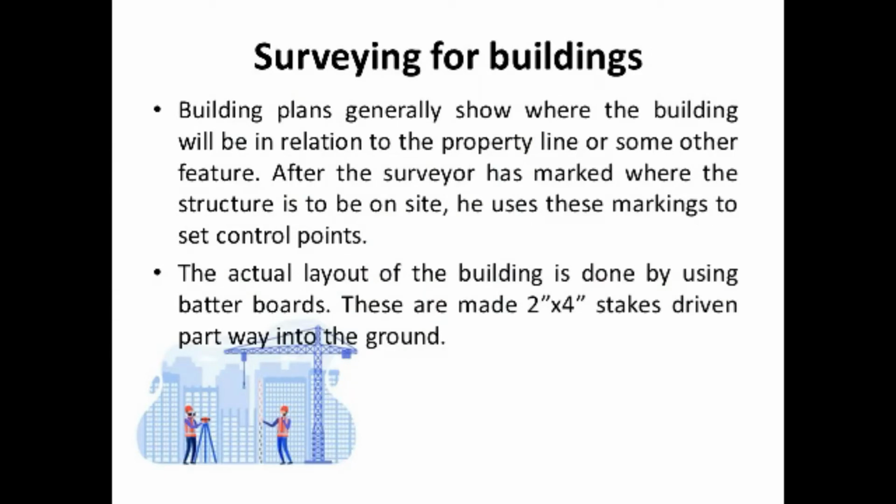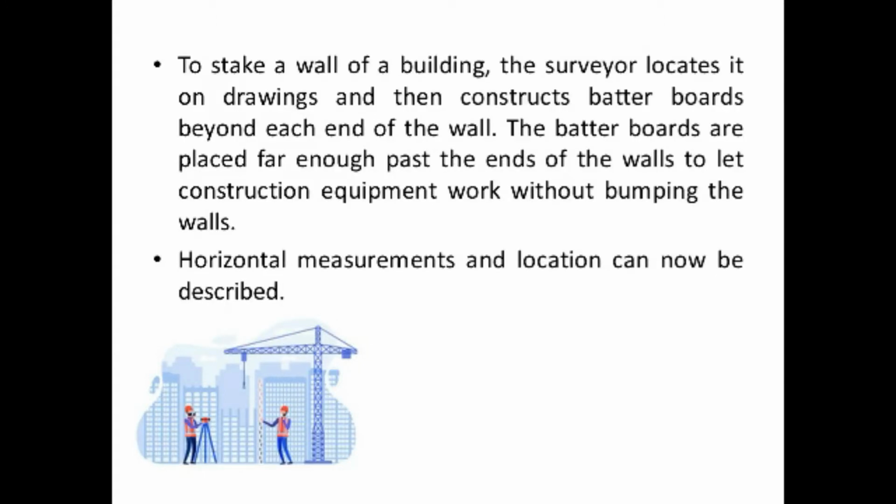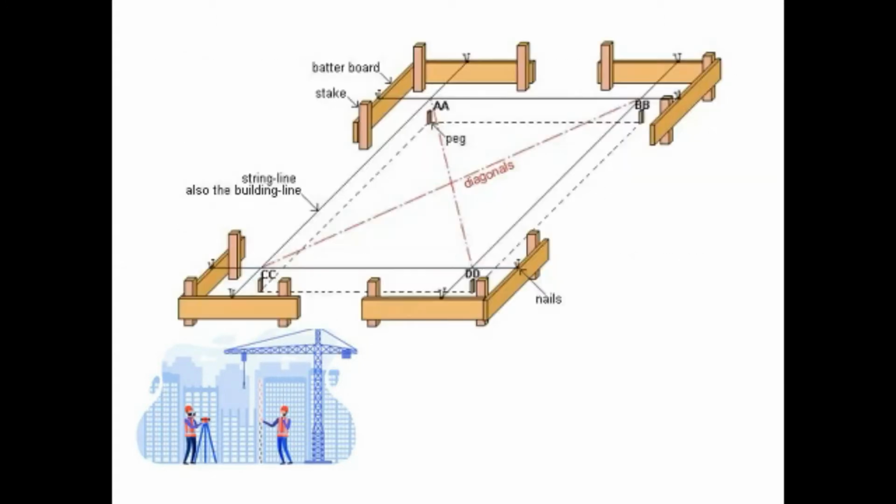The actual layout of the building is done by using batter boards. Mga batter boards ay may sukat na 2 inches by 4 inches at nagsisilbi sila bilang stakes driven part way on into the ground. Later, we're going to show an illustration of the batter boards. We have here an illustration. These ones are the stakes, and on the stakes, batter boards are attached.